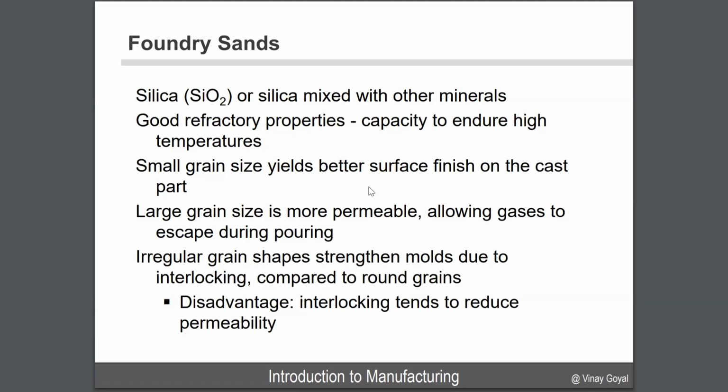I want to mention that a lot of things I say are not in the chart, so I hope that the audience is taking notes. These are very important things I'm saying. So this part that could have surface roughness, any surface roughness can become a stress concentrator. When this part goes under cyclic loading conditions, it can initiate a crack prematurely and then propagate. Combine that with potential defects within the part, and things can become much more of an issue.